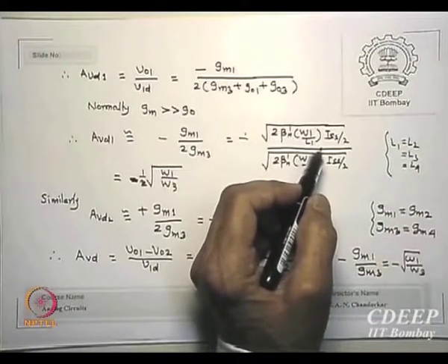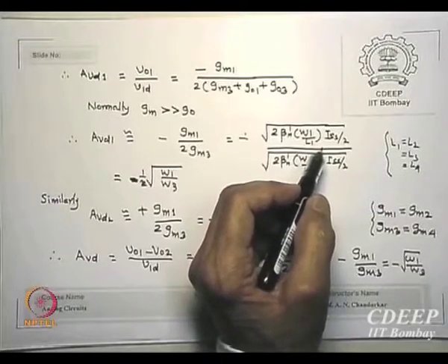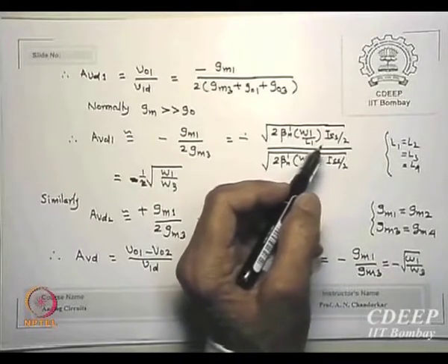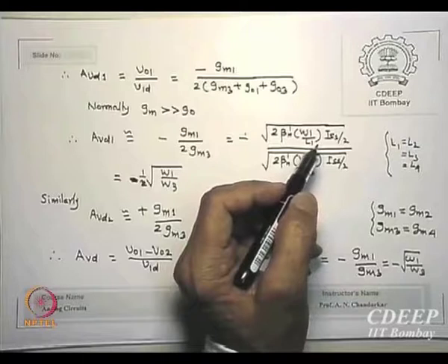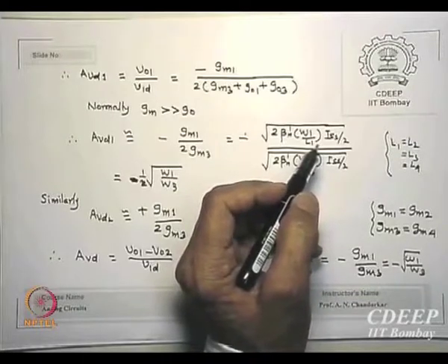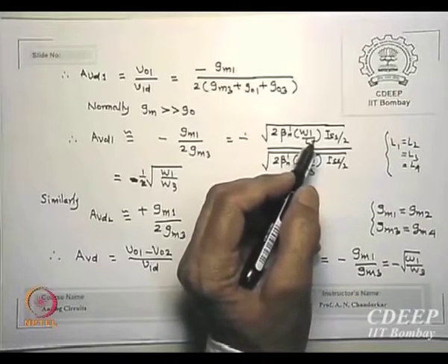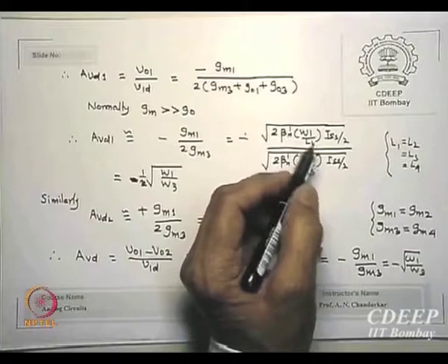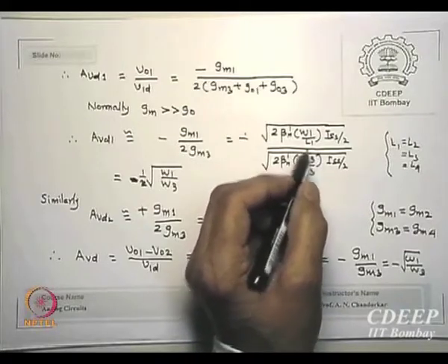Because 1 upon R plus 1 upon R plus GM, you have to invert it again, so if the expression becomes long, add conductances if they are in parallel. Is that point clear? Whenever you have parallel things, you can convert them into their G's and add them out. Essentially when you want to know R, you will have to do 1 upon again. But it is much easier to do with conductances.